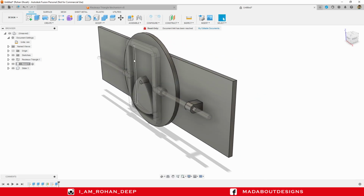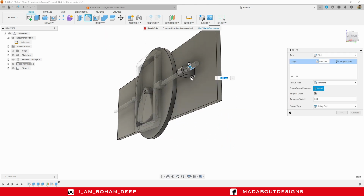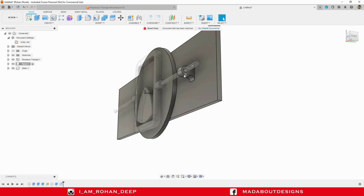Now go to Fillet command. Press F to go to Fillet. Select these two edges and fillet them up to a radius of 10 mm. Press enter.